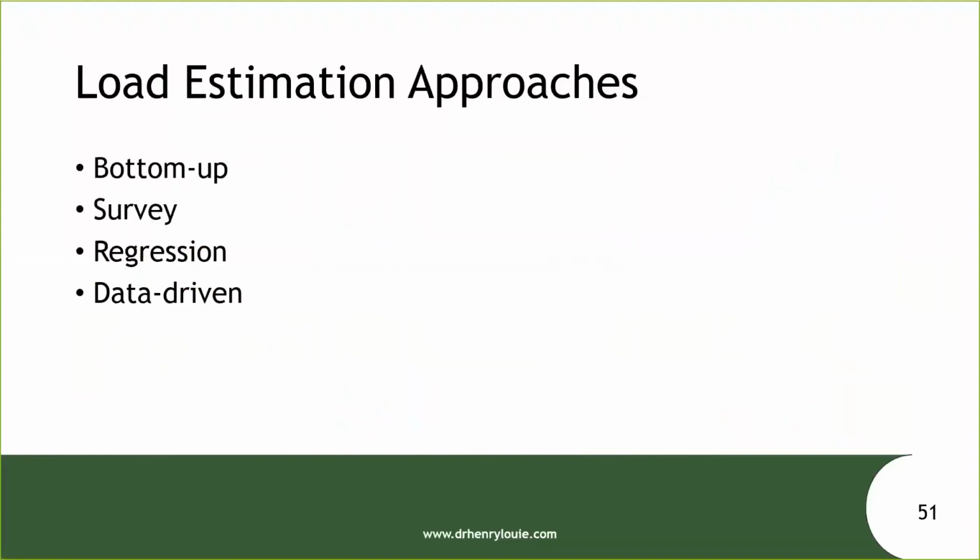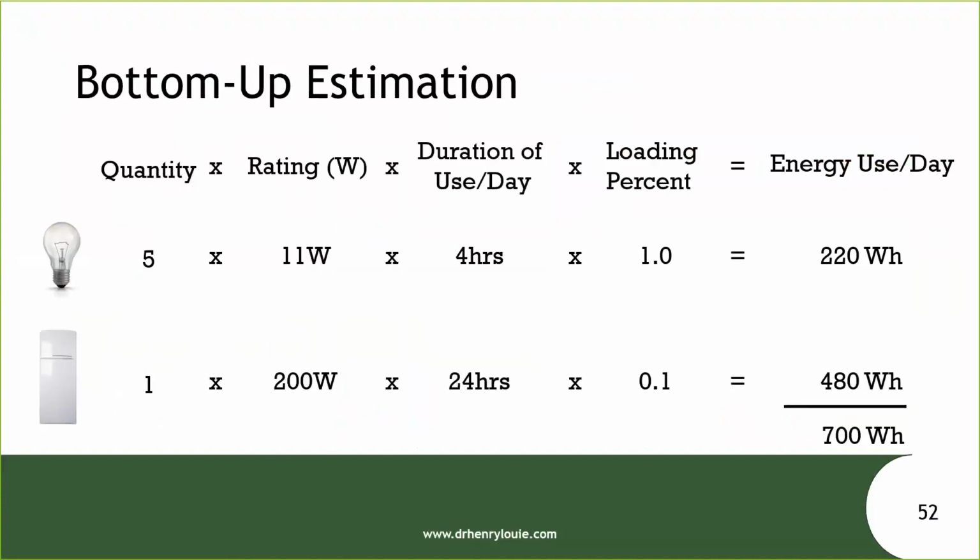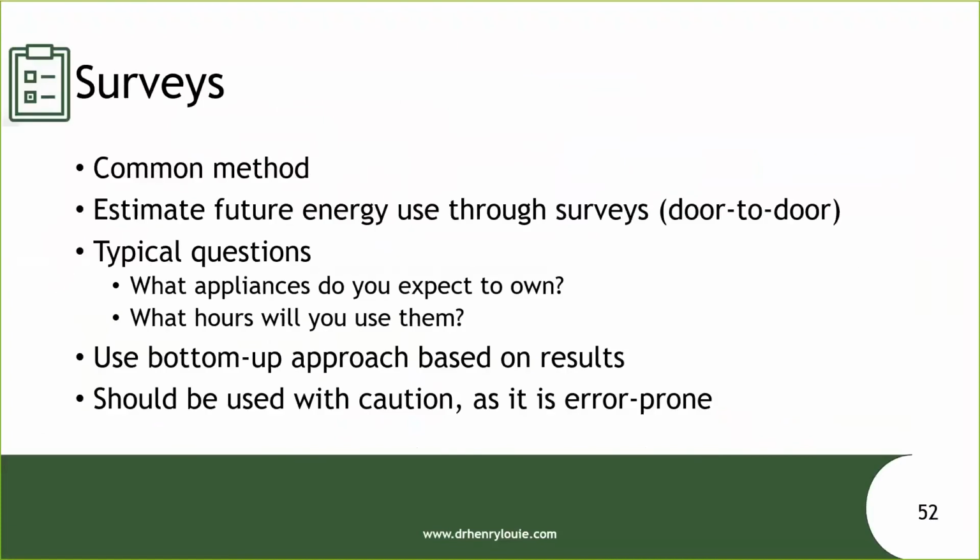But you need to do a load estimation to understand how large of a system that you want. And there's several different approaches. I'd say one of the most common is the bottom-up approach or the survey approach. In the bottom-up approach, you basically look at all the components, all the appliances, how many, what their rating is, how long they're going to be used, and if they're going to be fully used, and you come up with a daily energy use. And you do that for every component, and then you just simply total it, and that gives you your energy demand.